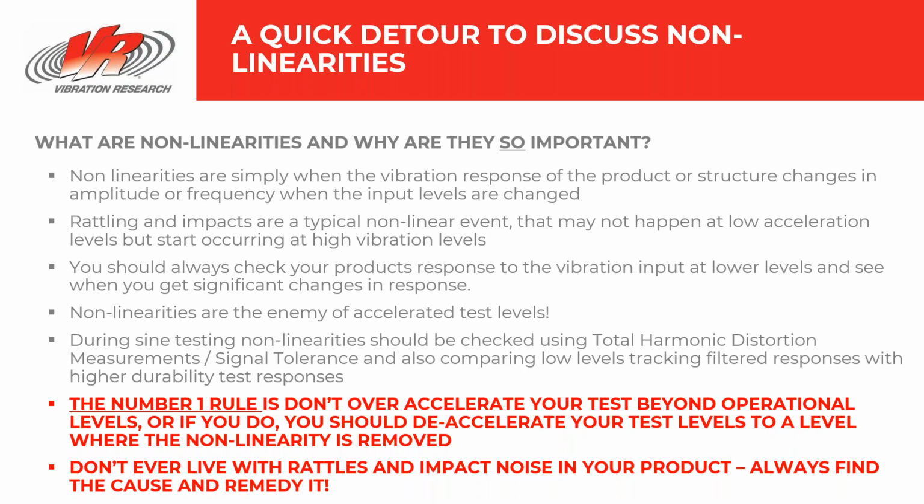The number one rule is don't over-accelerate your test beyond the operational levels, or if you do, you should check, and decelerate the test levels to where non-linearities are removed. And don't ever live with rattles and impact noise on your product. Always find out what the cause is and try to remedy it, because rattles and impacts are only going to cause problems in service.